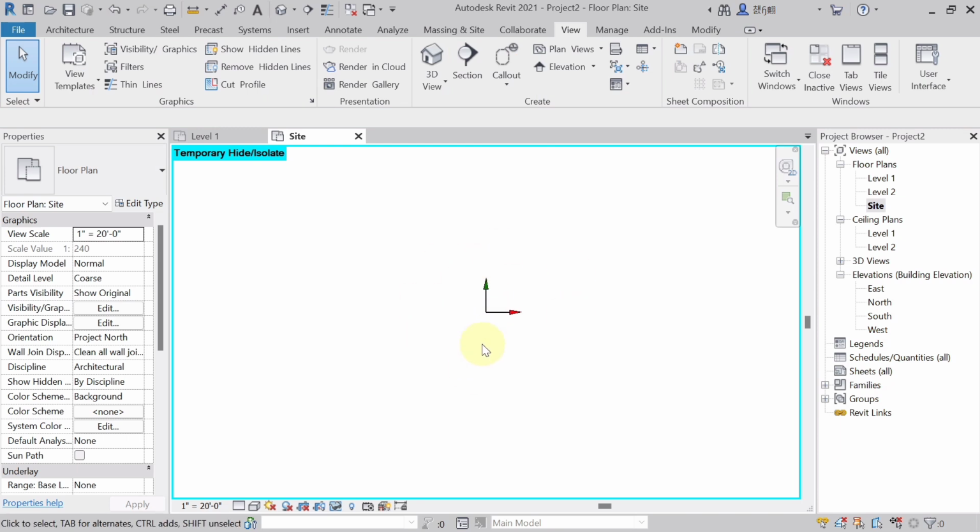Remember, this internal origin point is invisible and always at the 0 coordinate, 0 0 0 in Revit. By default every import and export will be in relation to this point and it cannot be changed. Suppose if you want to select it, see it is selected. If you want to move this internal origin point, it will not move. See, when I'm trying to select, it is not selected.